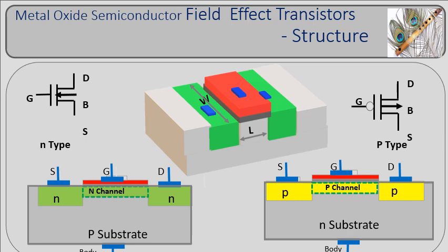A metal oxide semiconductor field effect transistor is a key component employed in switching and amplification applications. It is made up of source, drain, gate, substrate and a thin oxide layer. Most transistor structures are fabricated using several overlapping and isolated layers that result in the creation of parasitic resistances and capacitances, which in turn limit the device performance.